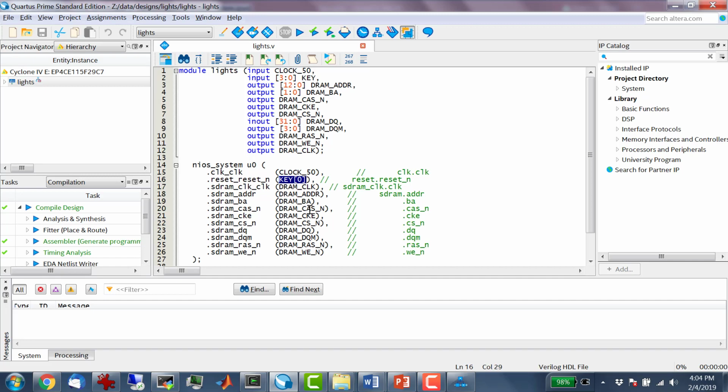So I'm connecting the right key, which is active low, to reset_n. This button is going to go straight to the reset. That's apparently a convention, because in the sample demo design that comes up automatically, if I hit that button, it freezes. So it looks like Altera or Intel is using that same button as their reset as well, based on the behavior when I push it, right?